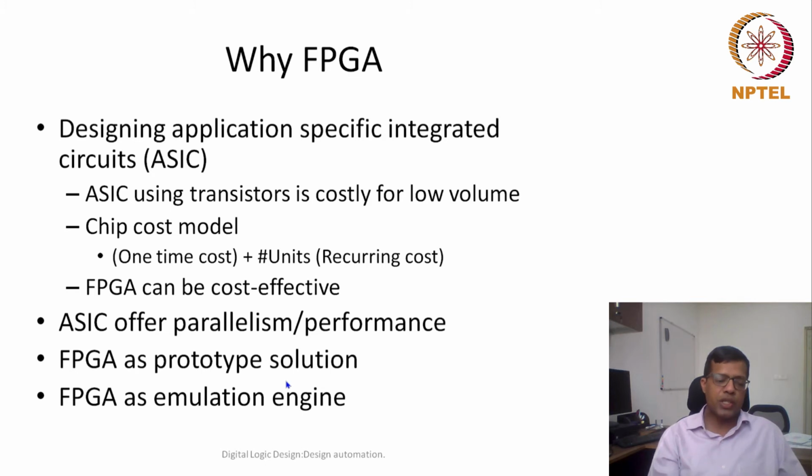Emulation engine means that you finally would like to design an ASIC, but an FPGA can serve as an emulation engine so that we can quickly emulate that final design, and then we can use this FPGA for debugging or for performance checks, etc. So these are the various use cases why FPGAs are used.